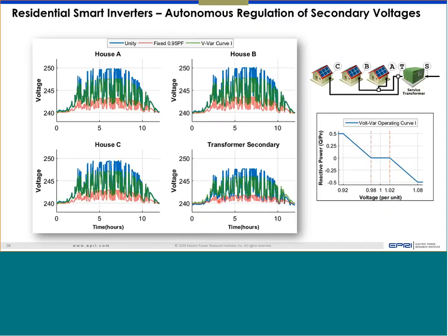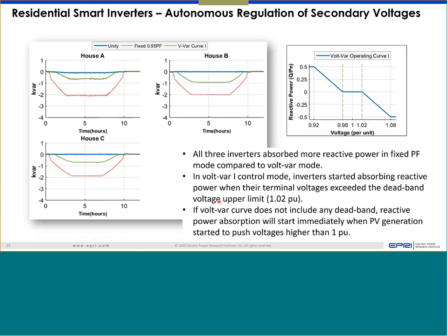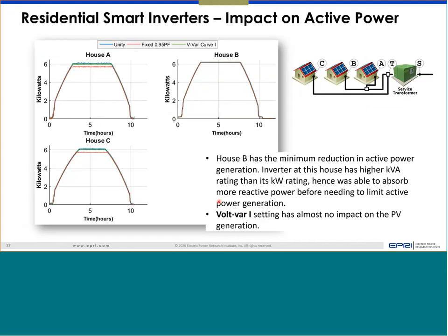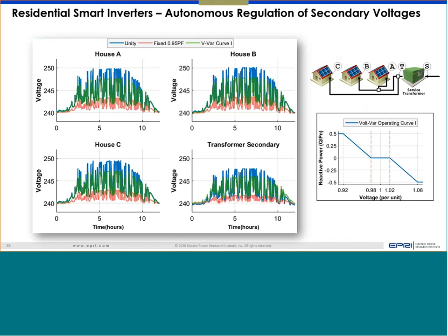Okay, same example, just showing it for a highly variable day, because these are all clear days, perfect sunny days. But what happened on a highly variable day? You can clearly see the voltage going up and down, up and down, up and down all day. This is real data. The irradiance came from a site where we had the measurement. We put this irradiance into a PV simulator and then exposed the inverter to these three different settings under the cloudy condition, with the actual irradiance measurement from the site. So this might be somewhere in Florida, this type of variability.